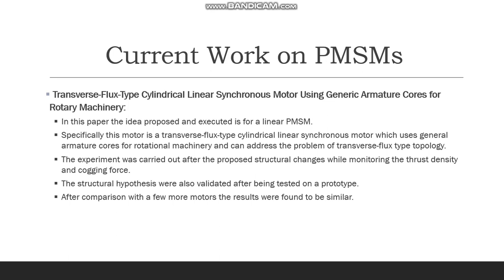The experiment was carried out after the authors proposed the changes. They designed the experiment and they monitored the thrust density and the cogging force as a simulation first, and then the structural hypothesis was also carried out and it was validated after the 3D prototype was tested. After comparison with the few motors that are already in the market, it was proved that this motor is right up there to the mark, and it can be used as a linear PMSM for transverse flux type topology.